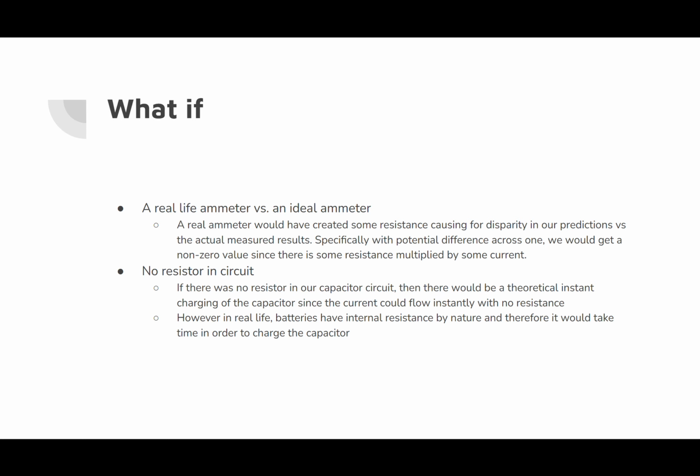If there was no resistor in the circuit, the capacitor would instantly charge in theory. However, in real life, batteries have internal resistance, and therefore it would still take some time. However, in the PhET simulation, it would theoretically charge instantly.